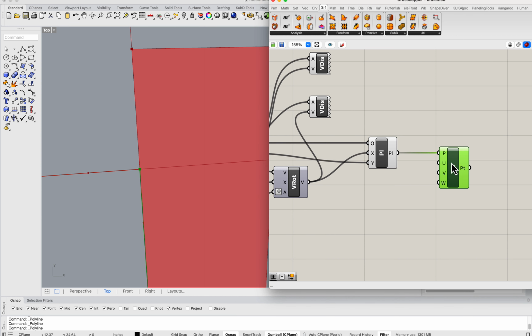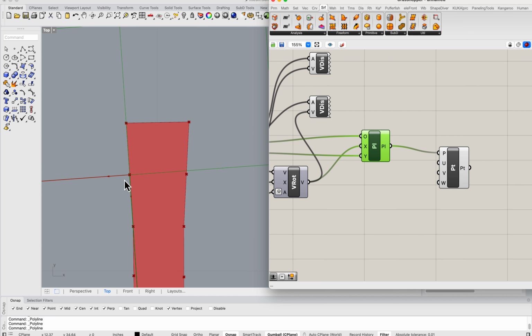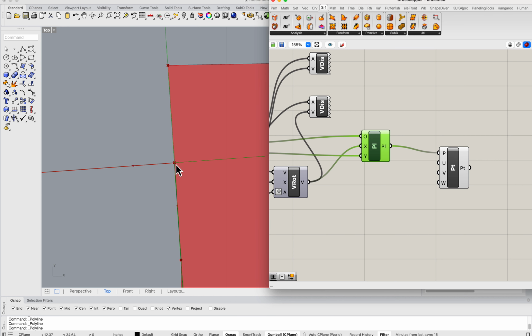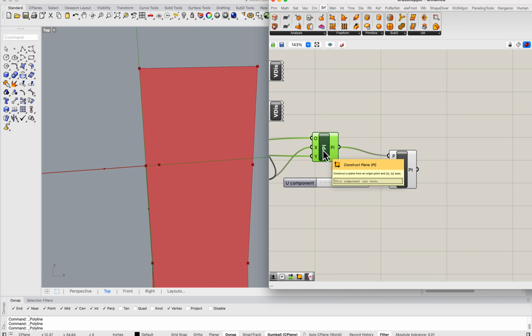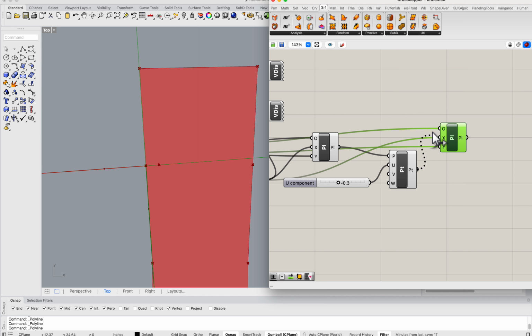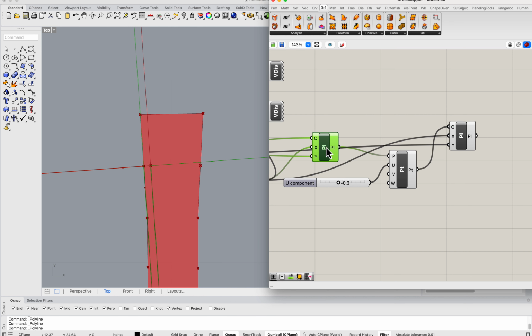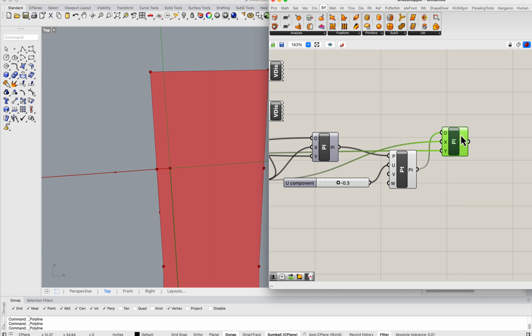So I get the constructed plane as orientation, and I want to move it in the negative direction of x. So that will be the u direction. So if you do -0.5 to 0, and if you move it here, this will be our offset for the plane. So I'm going to keep it at 0.3, and I'm going to make a copy of this initial construction plane and then move the plane origin there so that we can place a rectangle specifically on this plane that is offset.